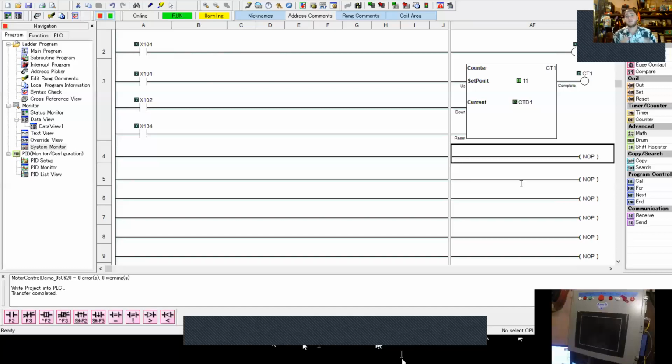Okay. And then on the math side, if you remember last time I talked about our scale for that output signal is 0 to 100, right? And our counter is running from 0 to 10. And so I'm going to write a little math function that takes that counter value and multiplies it by 10, so that basically every increment of my counter is a 10% increase in my VFD speed. Okay. So my counter value, if I look at this counter block here,